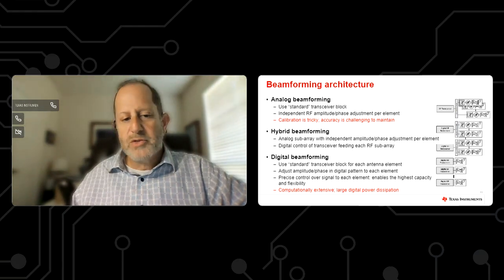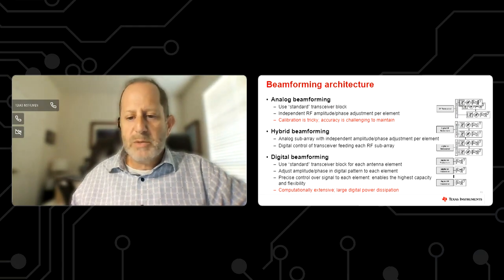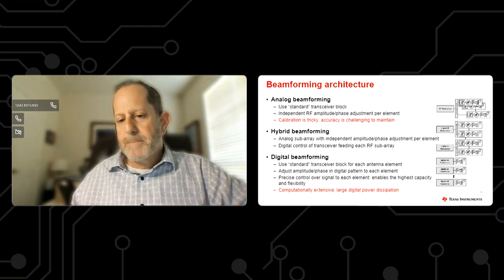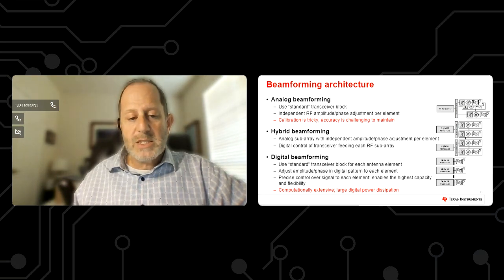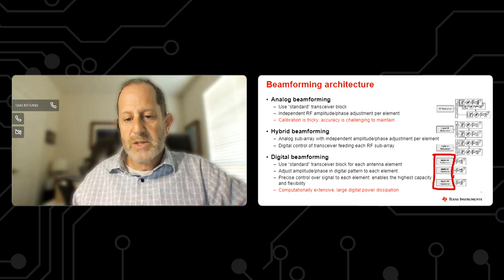With that precise control, I'll show that we have a lot more flexibility in moving beams around, multiple beams around, moving where nulls are going to be located to help in that situation. So this is really a nice system. We can utilize the RF sampling architectures for this feature to handle not only the conversion up to RF, but the gain and phase adjustment capabilities.